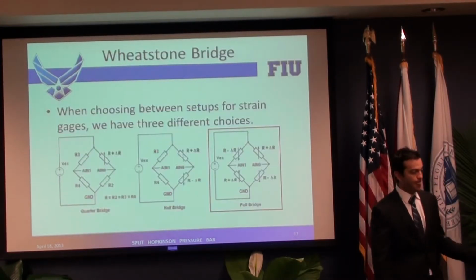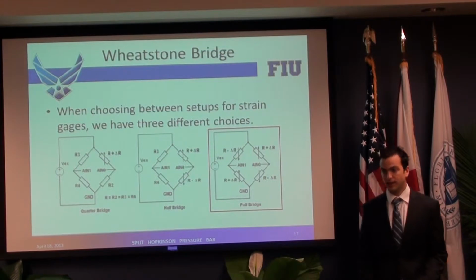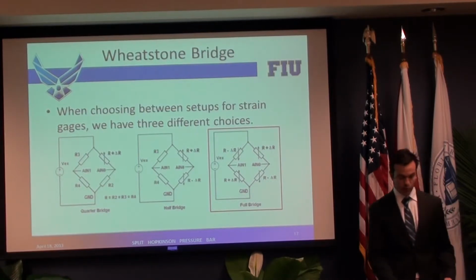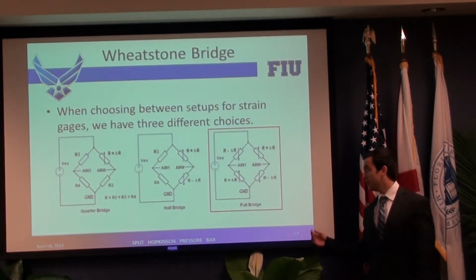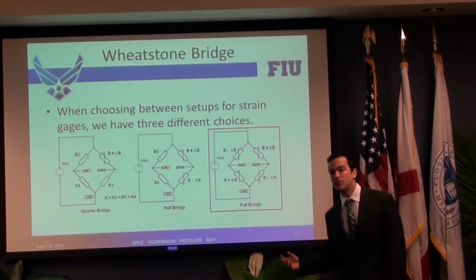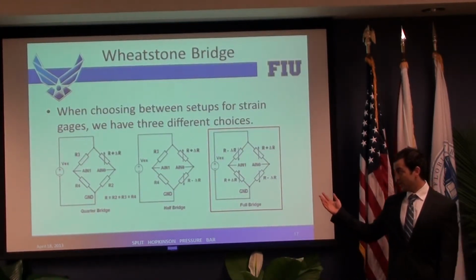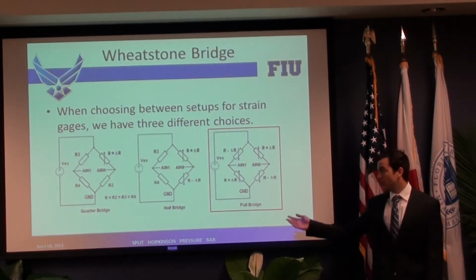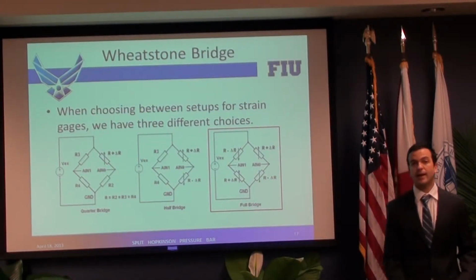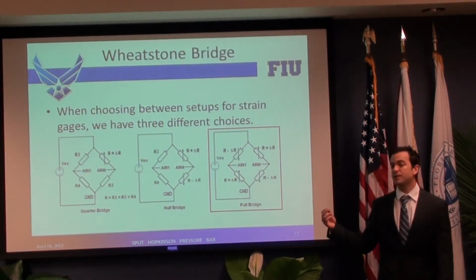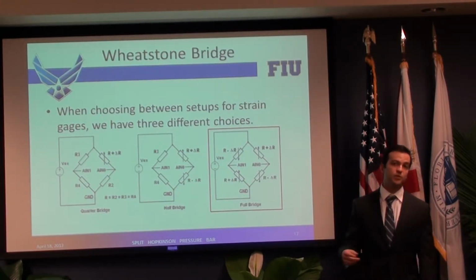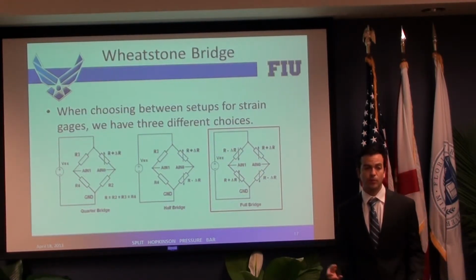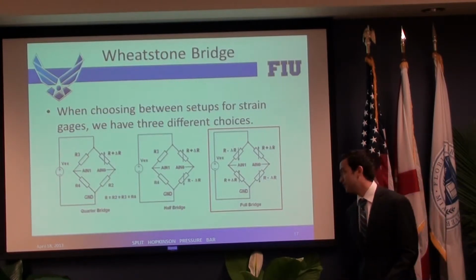These strain gauges will read the change of voltage, and it will be picked up by a Wheatstone bridge. A Wheatstone bridge is an electrical circuit used to measure an unknown resistance. If we place 4 resistors of the same capacity, making a bridge the way shown in the picture, and apply a voltage into the circuit, the voltage out will be equal to 0. So if we replace one of those resistors with a strain gauge, we will be able to know the change of voltage that is flowing through that circuit.